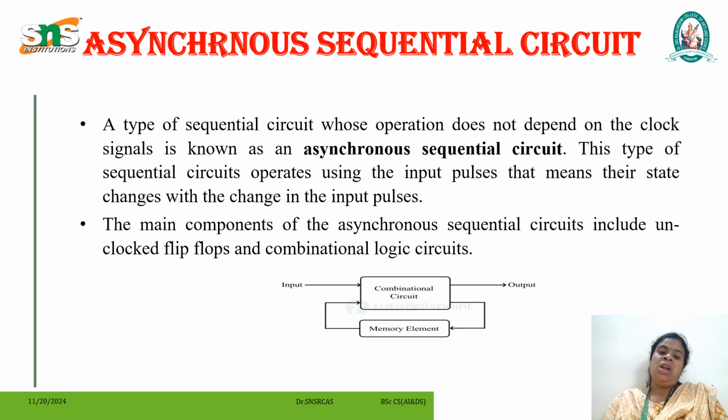Asynchronous sequential circuits are mainly used in applications where the clock signal is not available or practical to use. For example, they are considered where the speed of the task execution is important. Asynchronous sequential circuits are relatively difficult to design and their behavior is sometimes hard to understand. A ripple counter is a common example of an asynchronous sequential circuit.